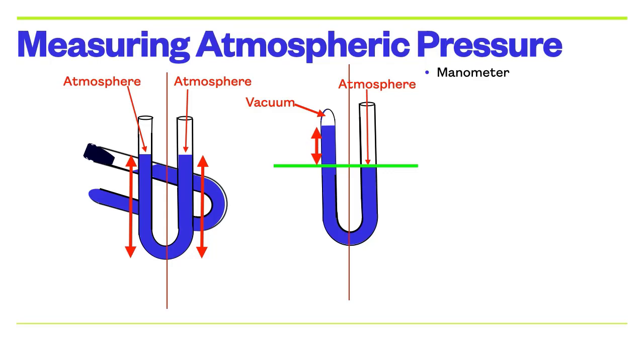So, as a result of using manometers, people began to just say, well, the atmospheric pressure is equal to the height of a particular column of fluid. And the fluid that was often used was mercury. In order to make the manometer as small and compact as possible, you want a liquid which is as heavy as possible. Well, mercury is an extremely dense metal which is liquid at room temperature. Now, it has some health hazards and it has some other issues, but in terms of being a liquid for a manometer, it turns out to be almost ideal. It works really, really well.